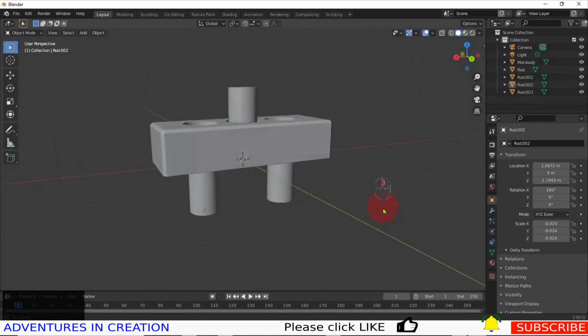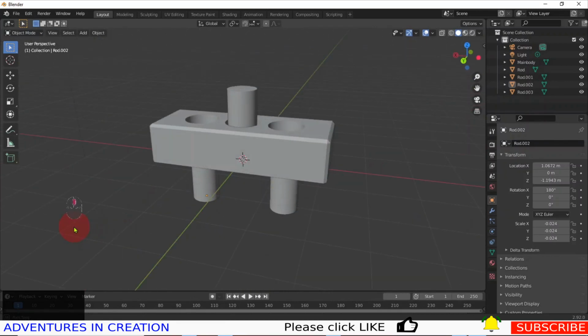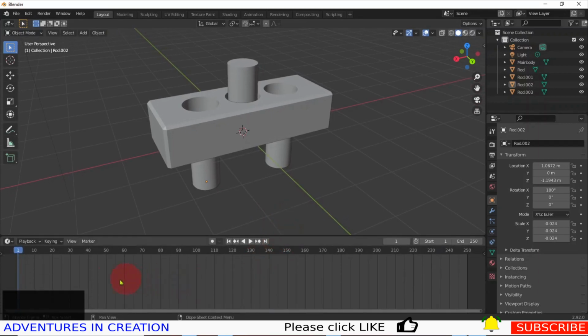Now to animate something in Blender, it's very easy because you can use what they call keyframes to tell it where it's going to be at any one time. So you really only need to have a couple of keyframes and you're all set. In this particular view, so we're in the layout view, we're going to go down to this line here, and we're just going to pull it up a little bit. And now if you look here, I have what looks like a timeline, or is a timeline. And if I press play, it'll play that. Nothing's moving because I haven't told it to move anything yet, but that's playing each frame.